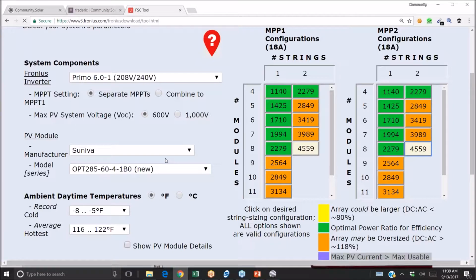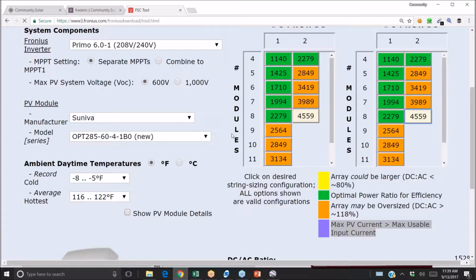And so depending on your application, if it's grid connected without batteries and you're selling all your power to the grid, we're oversizing our inverters by about 20%. In an off-grid setting, you might actually oversize the system by 40% or 50%, simply because you're going to have a surplus of electricity on sunny days anyway. It's really more about how you can produce more power on an overcast day.